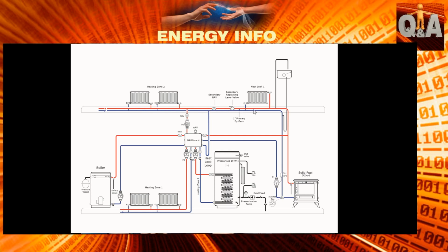What that's for is you can regulate how much water is actually going to flow back, so that you won't have the pump pushing all the water over to that open circuit. Remember, with a heat leak radiator, you try not to have it as half-inch pipe. It would be 3/4 or even inch pipe connected to the radiator. That drawing shows valves fitted, but really you're better off by far to have no valves on any heat leak radiator, or if you do have valves, have lock shield valves that are fully open.